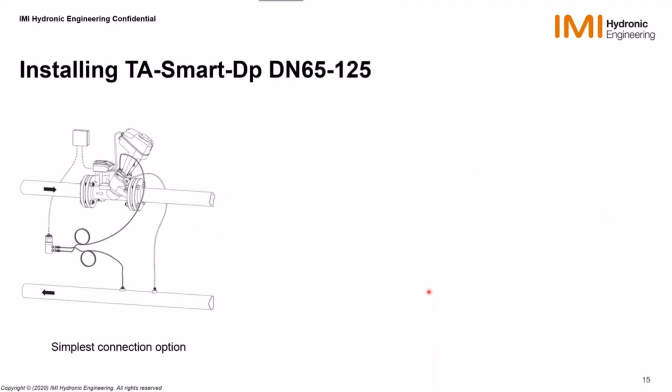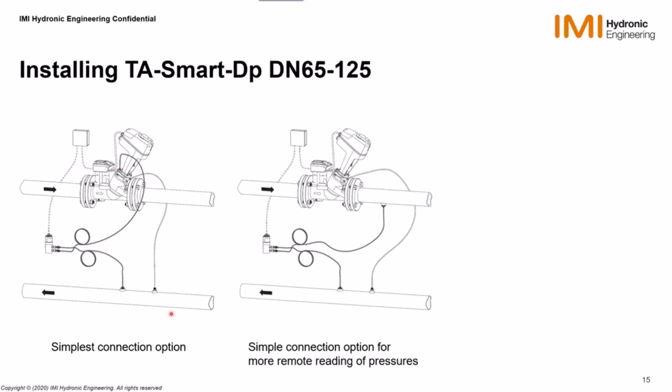In case of the large DP controllers, well, it's quite similar, but you get one capillary pipe into the valve, one capillary pipe into the pipe. You have an alternative to get 2 capillary pipes into the pipe because we provide these 2 connectors. This is when you have to go and read the pressure more remotely, more away. And also to be considered, the distance here can be increased because you just need to increase a little bit this cable, not too much. It's a 0-10 volts. So you have to be careful. If it is too long, you will get induction.